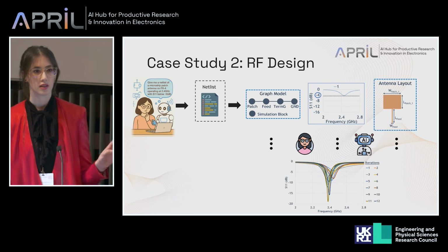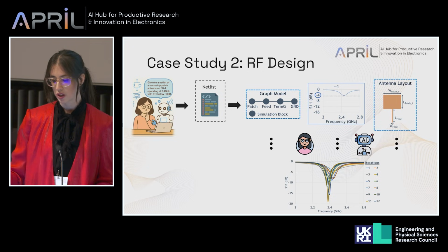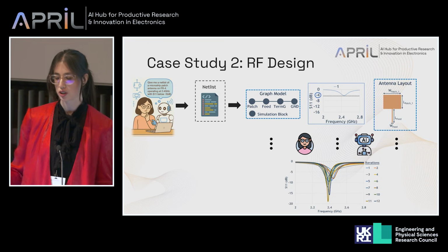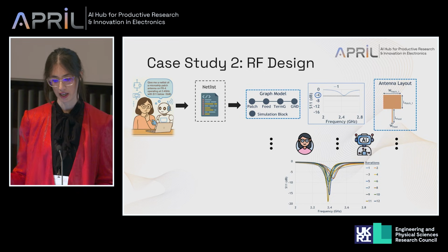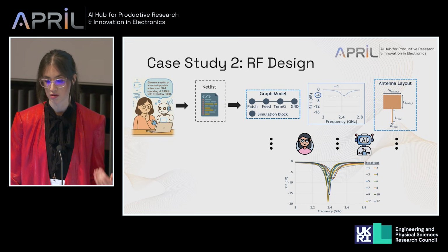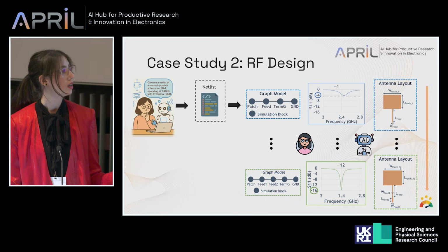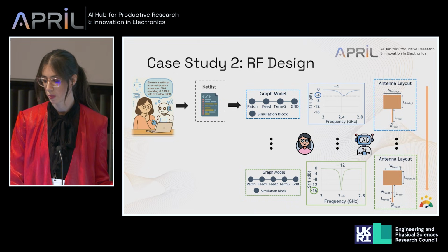With human and AI co-interaction, we can see how S11 is slowly becoming lower and lower according to our requirement. After 12 iterations, we reach the S11 we wanted, and even better. You can see in the plot that we even reached -16 dB.